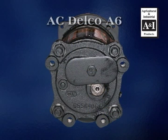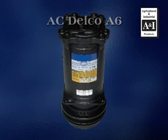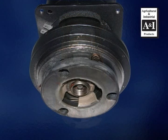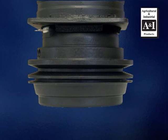The Ag AC Delco A6 compressors are all relatively the same. The difference is that the coil terminal location is determined by clock position, looking at it from the clutch side. This one will be called the 10 o'clock position coil. The pulley also needs to be identified by belt groove width, 1 or 2 grooves, and outside diameter.